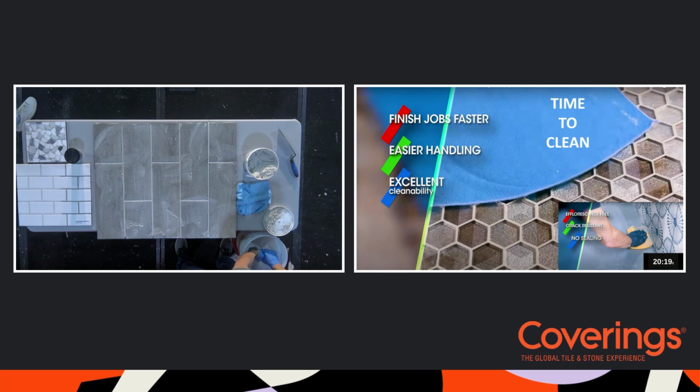The other benefit, if I get a grout haze, which you will on larger jobs, that's normal. The next day, the first gen is virtually impossible to clean. First generation premix would require a chemical cleanup the next day or thereafter. With this second gen Prism SCG, no chemical cleanup required, only water. That's it. So now we've moved away from harsh chemicals, away from harsh chemical cleanups, and now we're just using water. And Mrs. Jones certainly is happy about that. She won't get mold, and there's no harsh chemicals in her house at the front end or at the back end to clean it up.